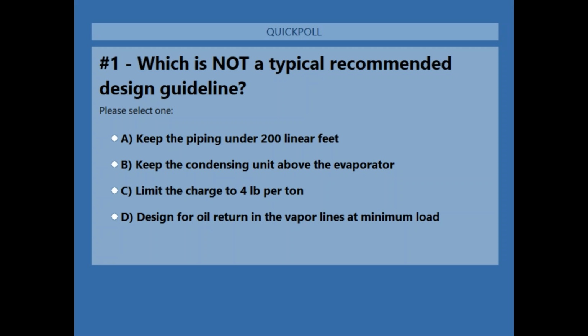We'll also tell you what size TXVs to use, because on some of these commercial jobs, it's not unusual to see 4 TXVs, 8 TXVs. You get up to the 100-ton, 130-ton range, 8 TXVs are common. So there's a lot of stuff going on there. It has to be correct. So we'll do the TXV sizing for you, as well as the nozzle sizing, and I'll get into the nozzles a little bit later too.